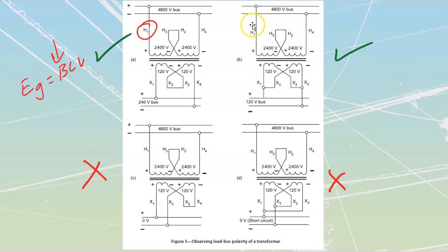This one over here, once again, same deal on my primary input side. It's getting proper connection. There's full flux. But now what we're doing is we are going to parallel our connections. Once again, H1 is instantaneously positive, so X1 is positive and X3 as well. And then we have our corresponding negatives. We're connecting this positive and this positive together and feeding that out onto a line.